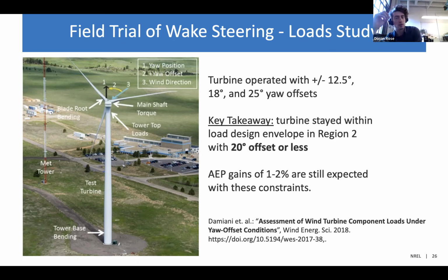Does that mean wake steering would only be used in region 2, or the lower end of region 3 too? Exactly, yeah. Unless you were doing it specifically for loads. We're probably getting into more topics of research now. There are papers where you could do wake steering to move a wake off a downstream turbine, because partial wakes are load intensive. You're doing wake steering for loads. That would give you a reason to do it in region 3.